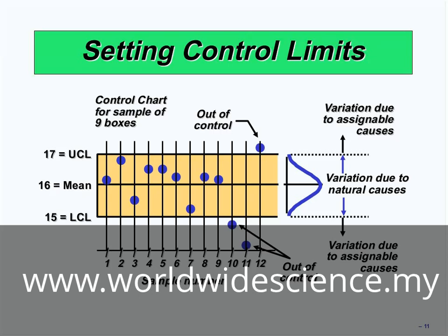Then you should calculate the acceptable range that are called UCL and LCL by formula. We talked about how you should use the formula, how you should calculate X and then X bar and finally X bar bar, because in the formula we need X bar bar.